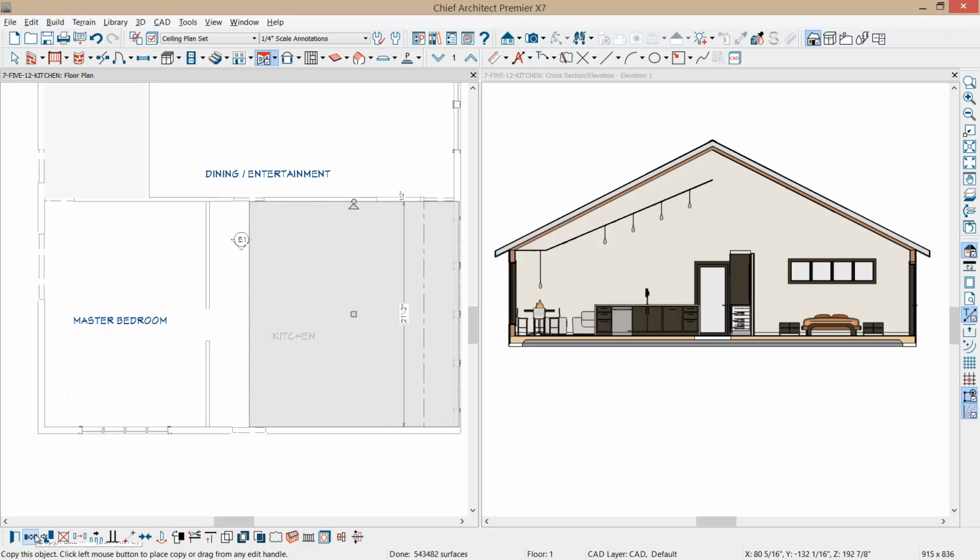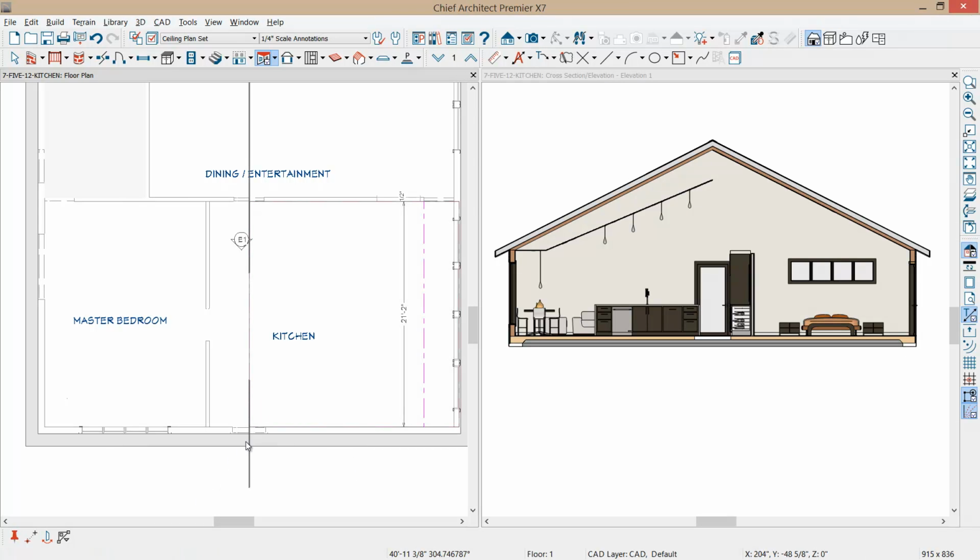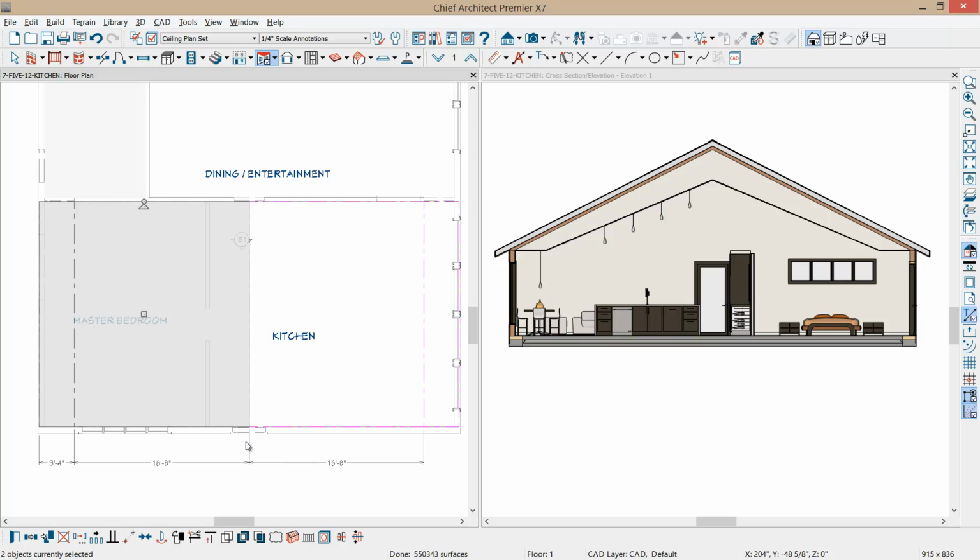Select the copy tool down in the lower left hand section of the screen, and then the reflect about tool, and we'll just come around right in here and reflect that ceiling plane in that view. Now you can see in the cross section the flat ceiling, the vault, continuing the vault into the bedroom, and that flat ceiling will then transition through the doorway into the closet area.